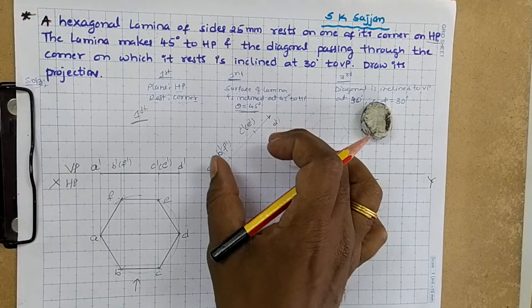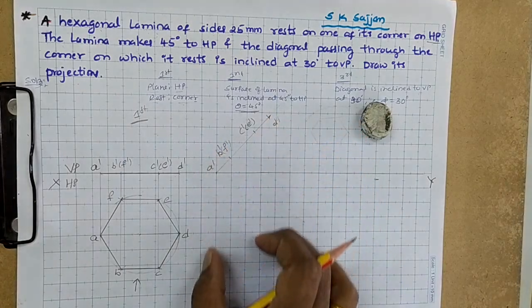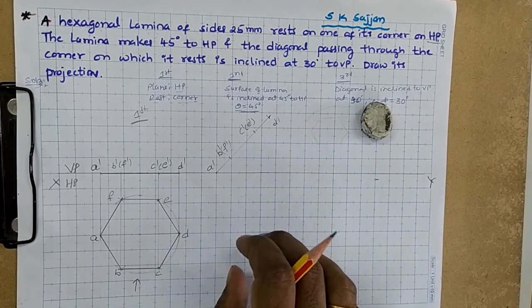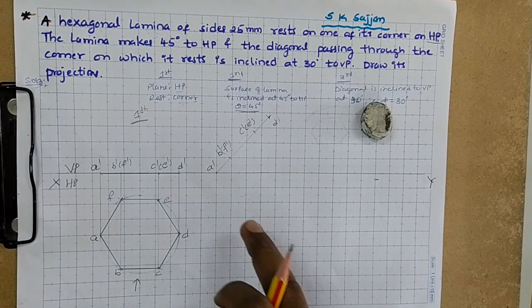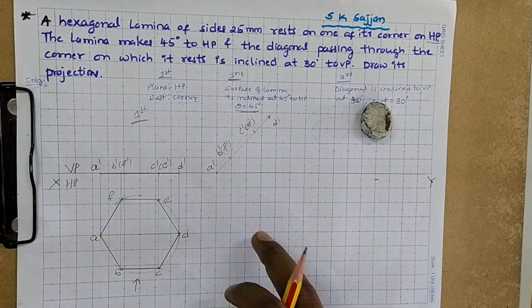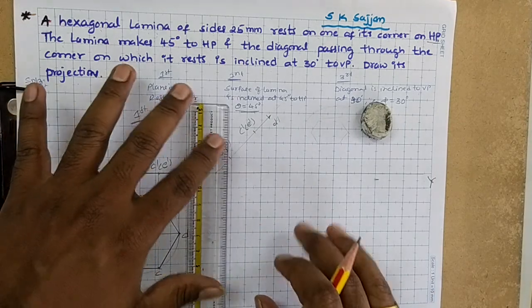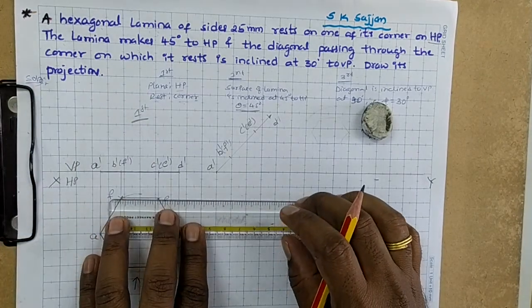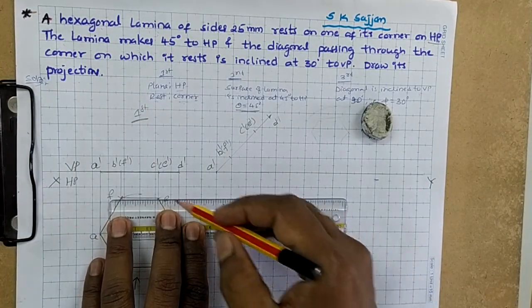and projecting all the points of the front view vertically downward. Where the horizontal projectors and vertical projectors intersect, mark the intersection points. By joining those we will get the top view. See, first I draw all the horizontal lines from the previous top view.